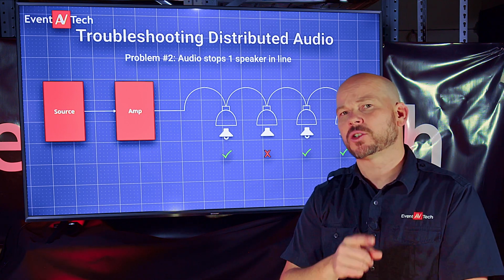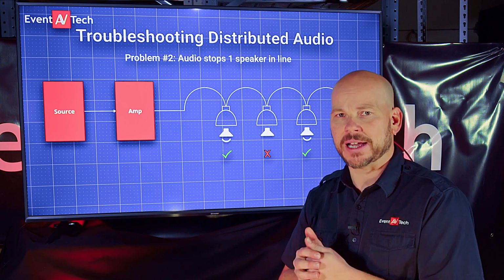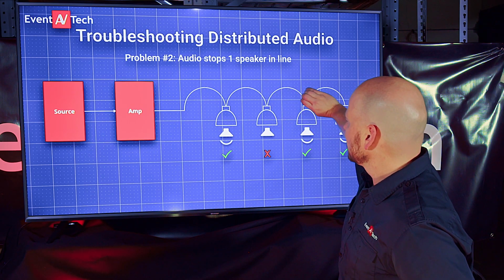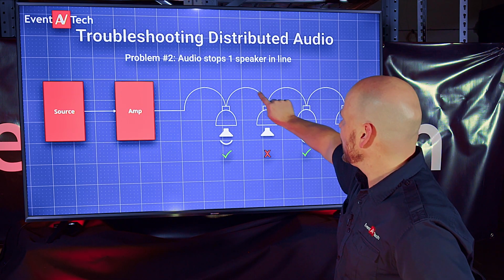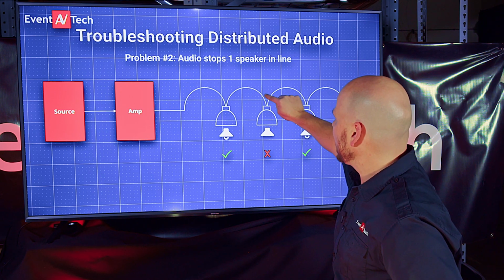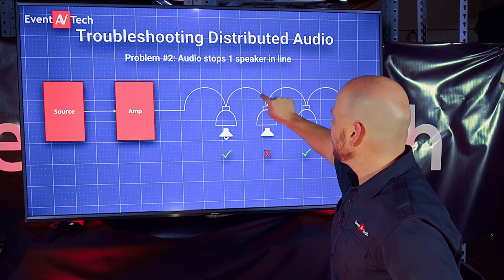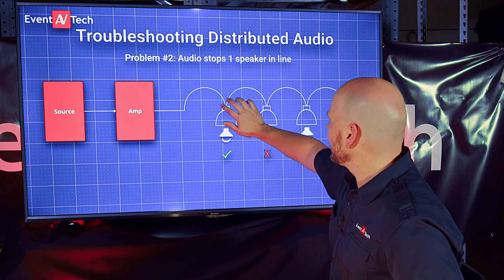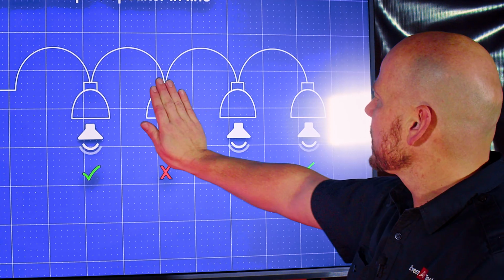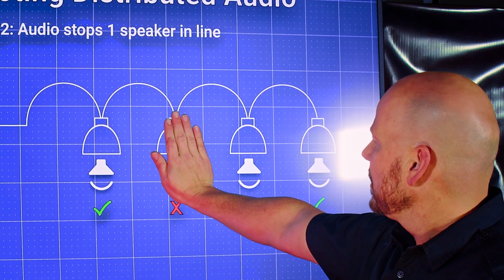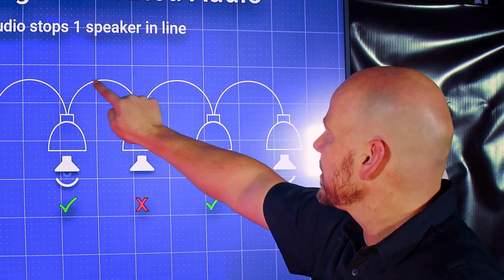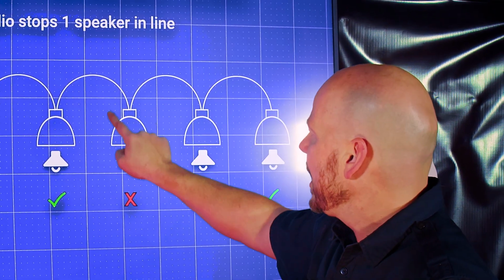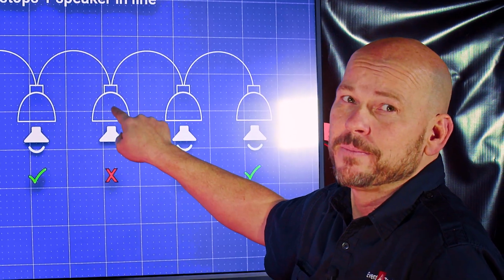So one of the ways that you could check to verify, do I have a bad speaker, is I could take my output out, and I could take this input, take it out, and I tie this input to this guy, and I bypass the speaker altogether. And if I can verify that that works when this is disconnected, then it gives me a good sign that this line is working fine. I don't have any problems with this line, and all of these lines are working fine, and my problem is actually right here.